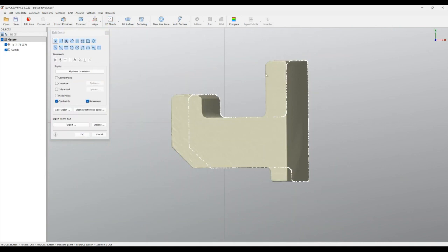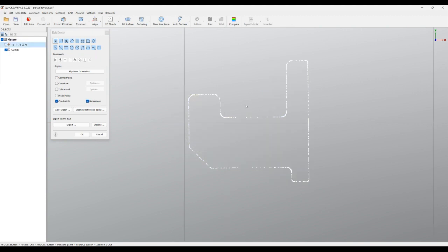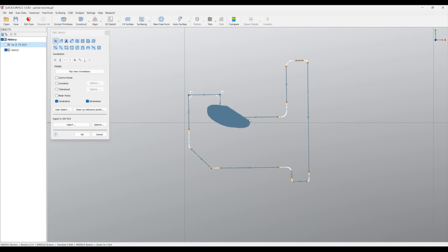The reason you see the mesh like this is because it's a revolved surface and it's actually turned around, and that's why you see the shape as it is. But I am not interested at the moment in the mesh. We'll quickly hold Control Shift to extract my lines like this, and we'll intersect my profile by using only the Control and brushing over the corners.